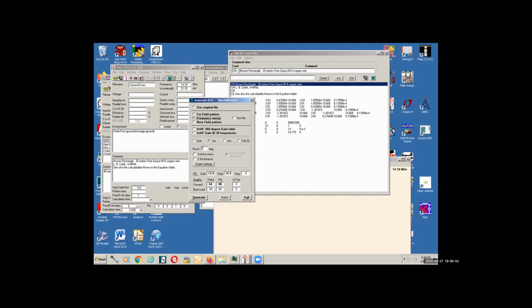You do the frequency sweep to get the feed point impedance over frequency. You can actually do near field, either E or H field, and it will compute the field levels around the wire. Basically you define a grid in X, Y, Z in 3 dimensions, and it calculates either the E or H field levels in that, and then it'll display that for you.